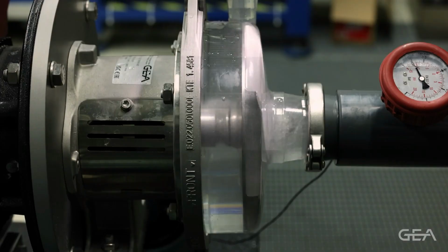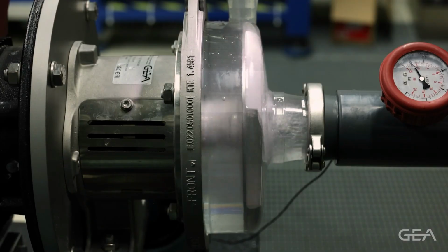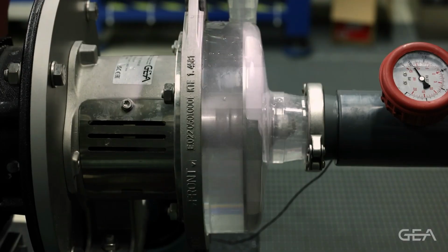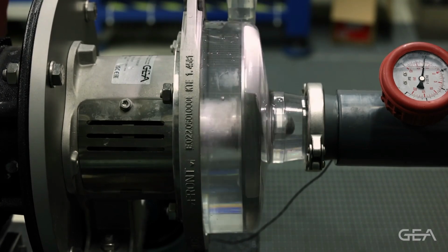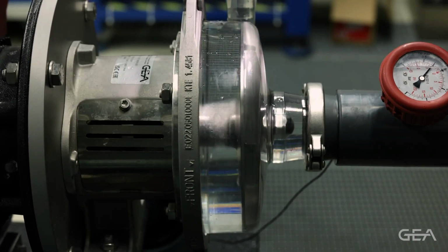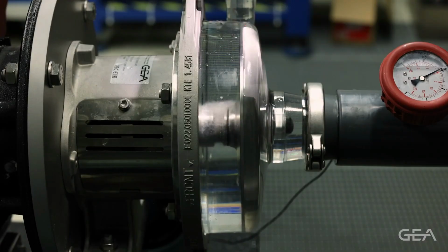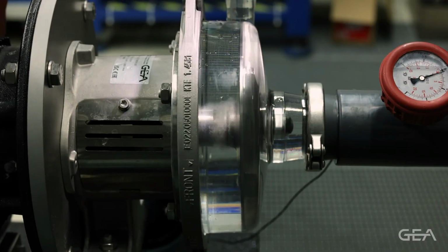Also note the mechanical seal. It's running with insufficient lubrication even after suction conditions return to normal. To prevent it, make sure the NPSH available always exceeds the NPSH required, ideally with a proper safety margin. Good system design and correct pump selection are essential to avoid these damaging effects.